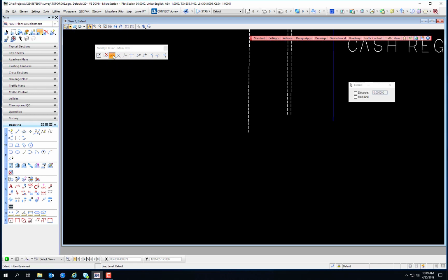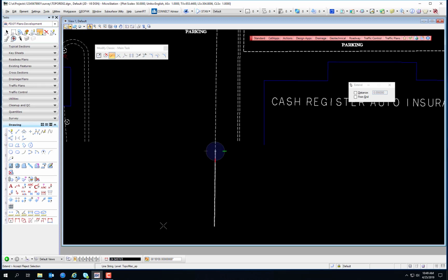All right. Extend line tool. Notice that it's staying in line with the angle at which the line was drawn. So different than the modify tool, because if you use the modify tool and grab this endpoint, you could move this line any which way to extend it. But using the extend tool constrains it to the actual direction the line is going.